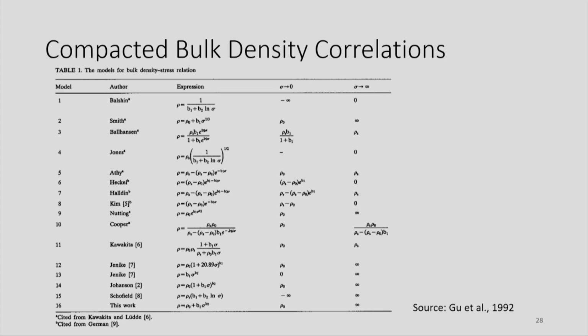Okay. So again, there are different compaction equations that you can use for relating the powder properties, change in properties. You don't have to worry about these again. Based on change in stress, you get the density of the powders. So at different stress values, you get the density. Again, there are tons of equations, but most common ones. We'll talk about the Heckel relationship, Kawakita. I'm not sure you would have learned about Jenike and Johanson. They have different papers, but the Jenike and Johanson theory is very common when it comes to bulk solids, storage and handling.